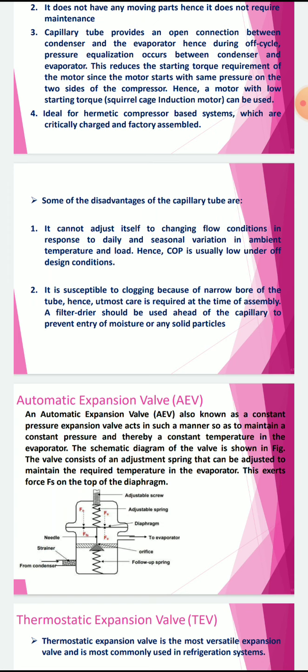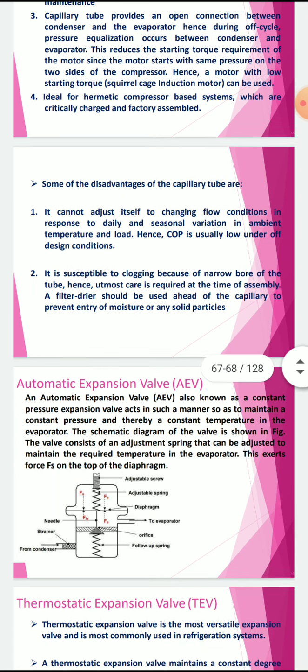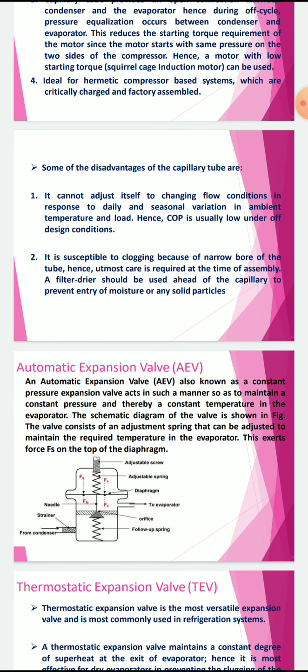It is susceptible to clogging because of narrow bore of the tube. Hence, utmost care is required at the time of assembly. A filter dryer should be used ahead of the capillary to prevent entry of moisture or any solid particles.